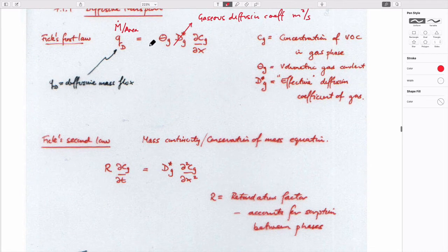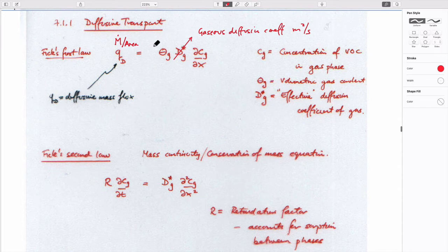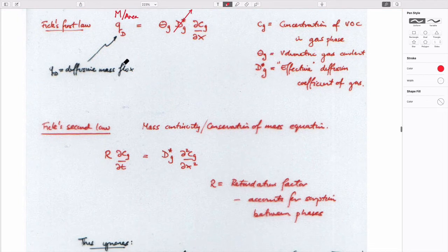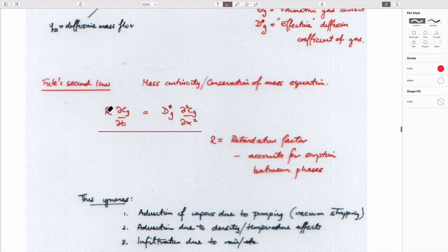And so in the same way that we dealt with the advection diffusion equation for transport dissolved in water, we substitute this flux, Fick's first law, into a conservation equation, which says mass in minus mass out equals accumulation. And if you do that, you end up with this diffusion equation, identical to the one that we had before. And identical to the one we had before is that it has a retardation coefficient, which we haven't said what it is yet. We'll have to define that, which we could imagine does something as a function of sorbing components onto the static solid phase.